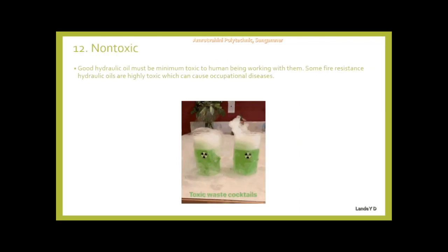12. Non-toxic. Good hydraulic oil must be minimum toxic to human beings working with them. Some fire-resistance hydraulic oils are highly toxic, which can cause occupational diseases. To ensure non-toxicity, it is important to select hydraulic oils that have been formulated with safe and environmentally friendly additives.